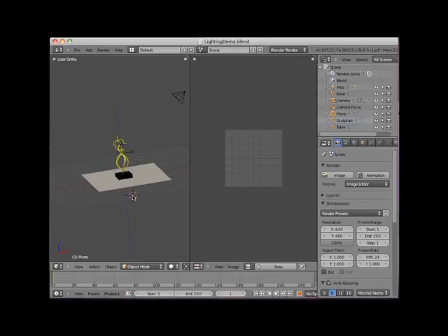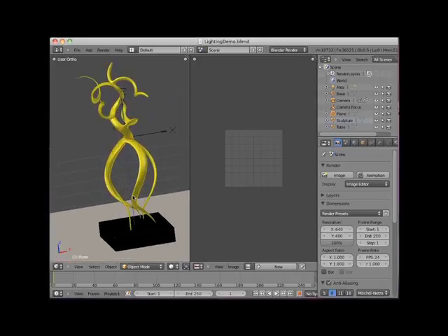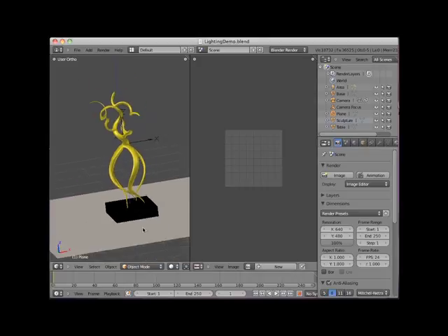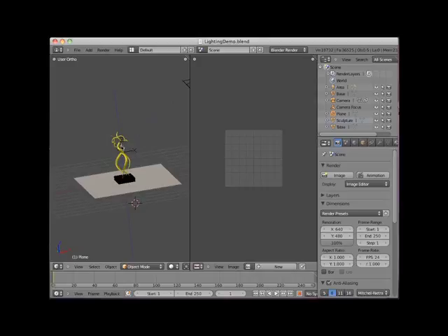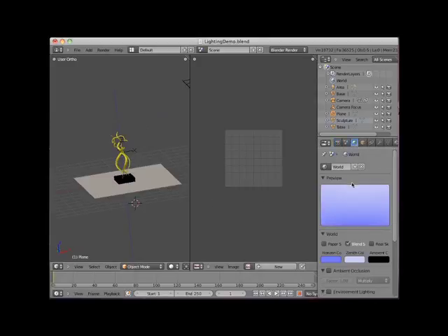To demonstrate Blender's Spot Lamp, I have placed in my scene a modeled sculpture and a base placed on a flat plane. The sculpture has a gold material attached to it, the base a mottled blue material, and the plane a cherry wood texture. In the World Editor, I have added a blue blended sky gradient. I have split my 3D editor into two windows, placing the UV image editor on the right, and have set the render output to display the rendered image in this UV image editor. I'll render the scene.